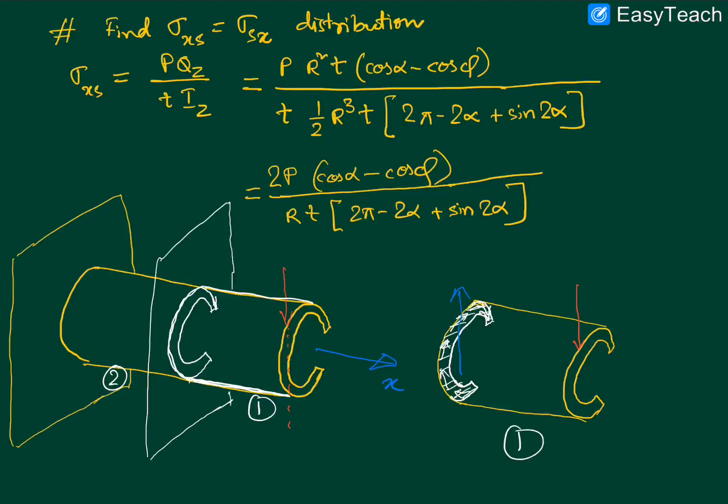It will also be necessary to have the force equilibrium. So as far as the force equilibrium along the y direction is concerned, we must have a shear force to balance out this externally applied load, and it is only through a shear stress distribution oriented in this clockwise fashion that such an upward pointing shear force will be present. But what about the cut piece 2?